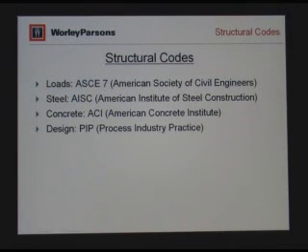So what you don't see here is the International Building Code. International Building Code really refers back currently now to the ASCE 7. So in the future, the International Building Code will by default say that for wind analysis or for seismic design, see section such and such of the ASCE 7. So basically it'll default to the ASCE 7.